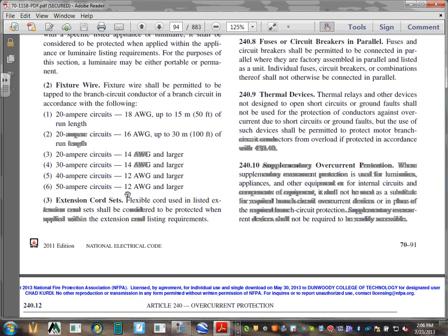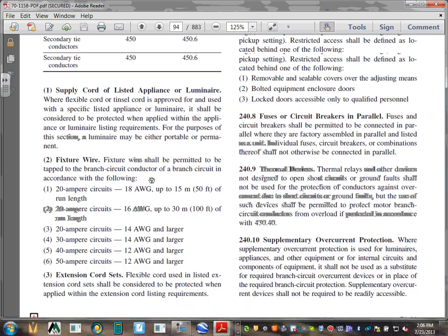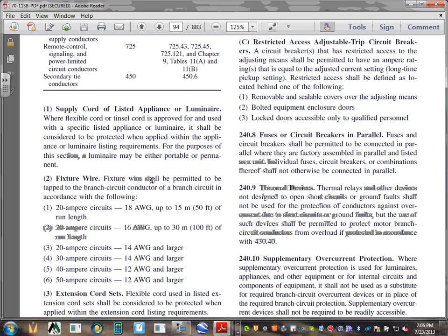The advantage of using 20 amp number 12 is you don't put all your eggs in one basket. If you have a 50 amp lighting circuit, 3-phase, you can put probably 2-3 stories in this building on one 50 amp, 3-phase, 277/480 lighting circuit, wouldn't you? I mean, if you have 50 amps, a lot of juice at 480/277 for lighting. But I thought these are really cool. A lot of people take advantage of them and make a system a little bit more unique.